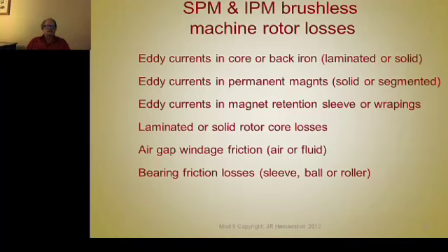You can have eddy currents in the magnet. So what's done there is to basically laminate the magnets. They don't call them laminations. They call it segmenting the magnets. You make a pole up of several magnets that are glued together before you finish grind or finish wire EDM or whatever you do to them. That's quite common. We're going to see some slides on that later when we look at the lecture on materials.